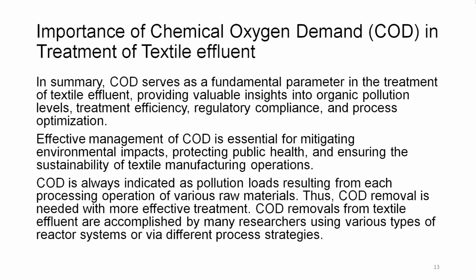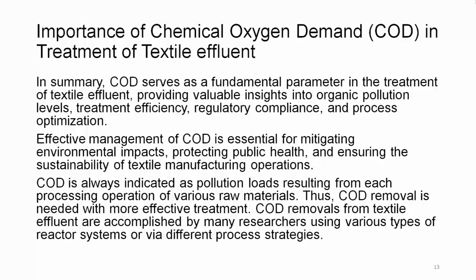COD is always indicated as pollution loads resulting from each processing operation of various raw materials. And we saw in one of the lectures that in each of the textile processing steps, whether it is sizing, desizing, curing, mercerizing, dyeing, printing or even finishing, each one adds on to the load of the textile effluent. Thus, COD removal is needed with more effective treatment.